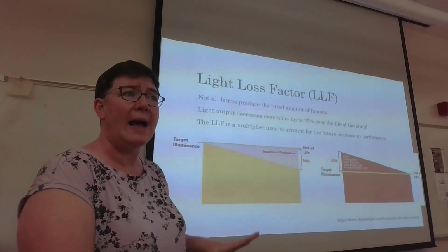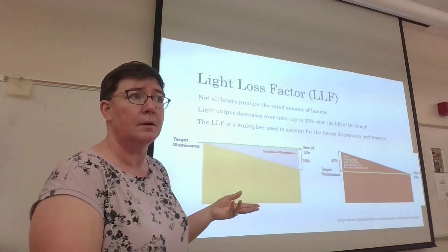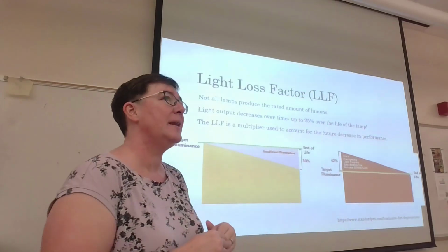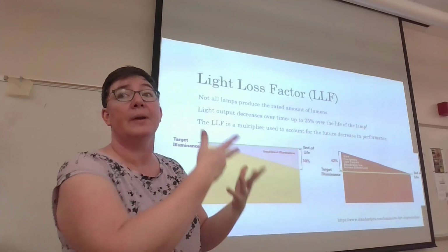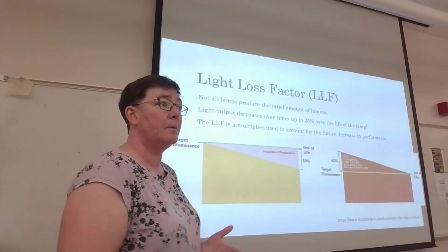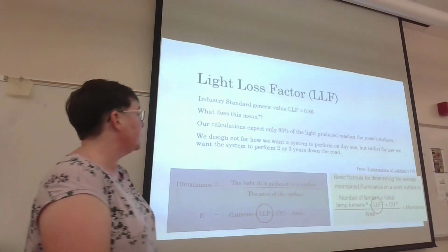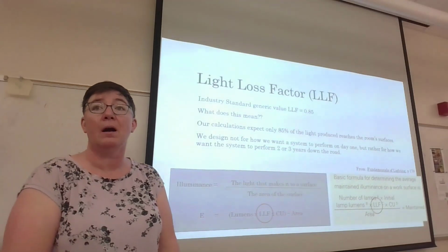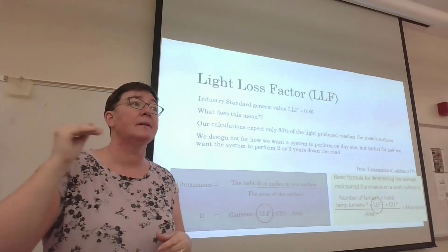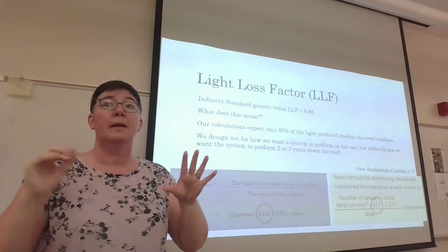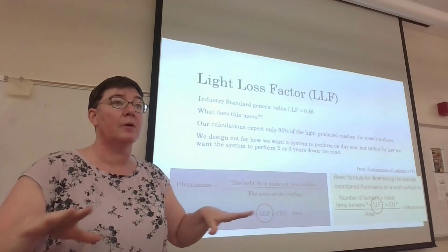Everybody clear on why we need a light loss factor? Yeah. Light bulbs get old, right? Okay. So we need to give a little boost to our original target illuminance to account for later on when the light bulbs are old. There absolutely are complicated data about exact light loss factors for specific types of lamps and specific luminaires. We're not going there in this class.